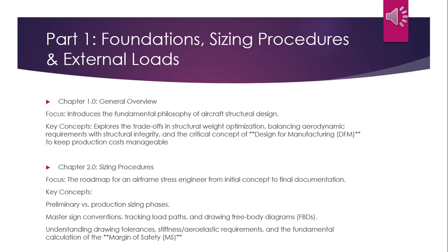Chapter 2 is sizing procedures. It focuses on the roadmap for an airframe stress engineer from initial concept to final documentation. The key concepts: preliminary vs production sizing phases, master sign conventions, tracking load paths, and drawing free body diagrams. Understanding drawing tolerances, stiffness, aeroelastic requirements, and the fundamental calculation of the margin of safety.